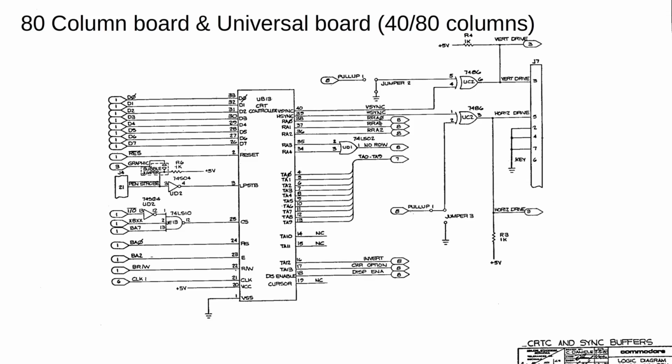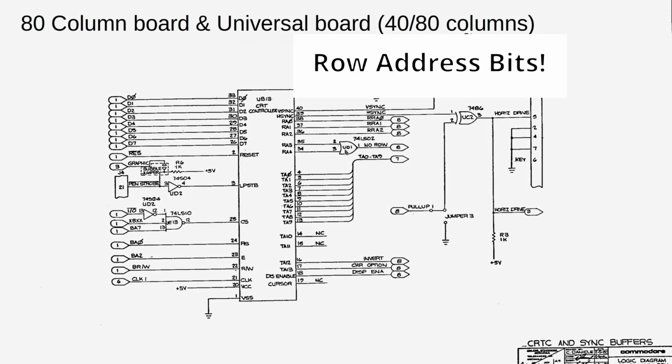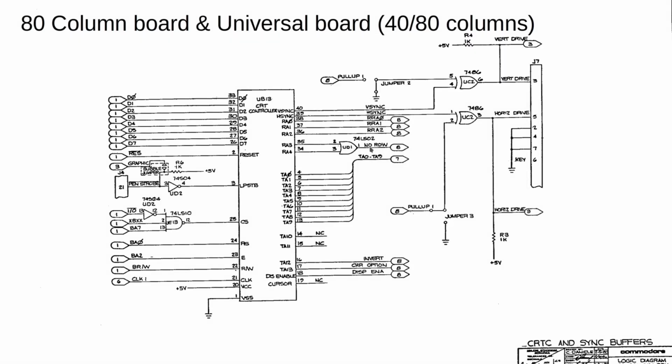Here the raster line, I didn't mention that in the previous slide. This is input to the character ROM. Again, the upper raster lines are actually here to switch off the display. So that's also in the other one. But the rest is basically some inverters for the vertical drive and horizontal drive. It depends on the screen you're actually using. So that actually concludes the schematic deep dive.